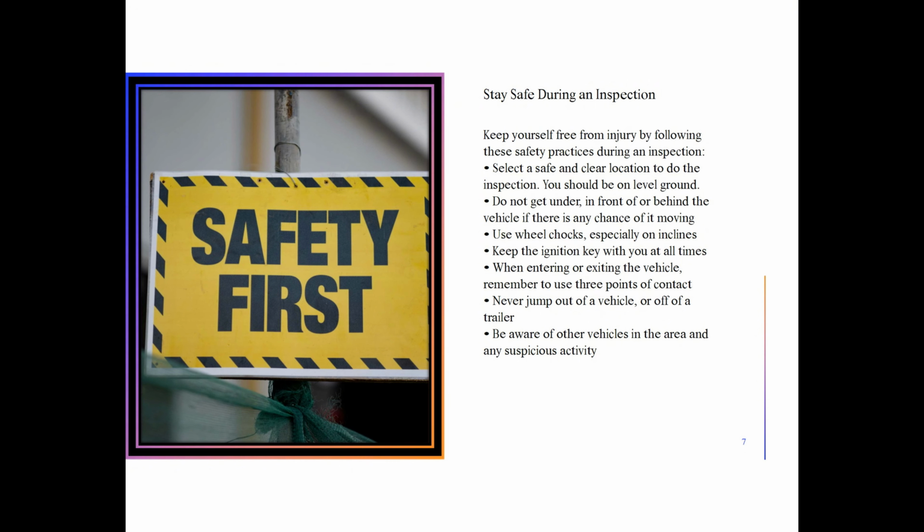Do not get under, in front of, or behind the vehicle if there is any chance of it moving. Use wheel chocks, especially on inclines. Keep the ignition key with you at all times. When entering or exiting the vehicle, remember to use 3 points of contact. Never jump out of a vehicle or off of a trailer. Be aware of other vehicles in the area and any suspicious activity.